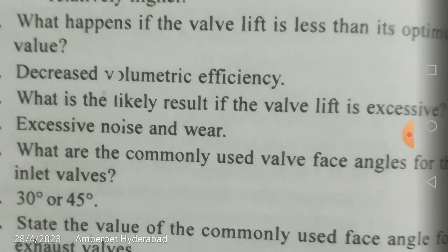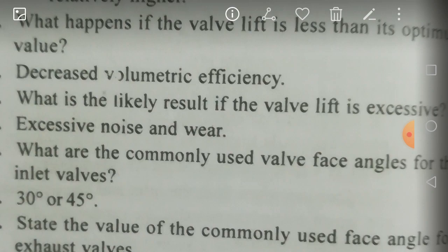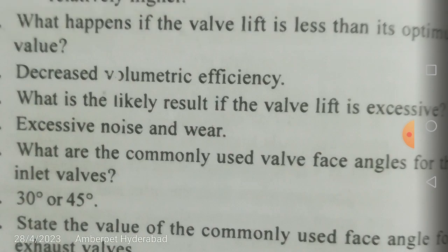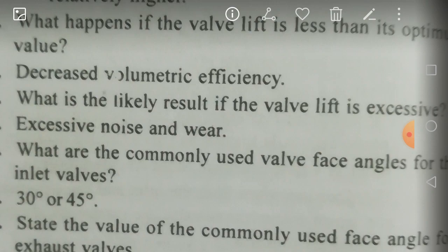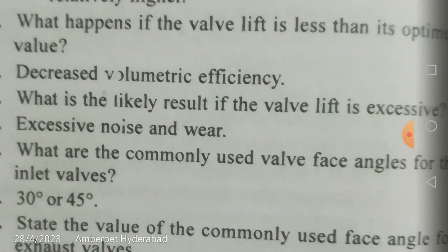Why? Because valves have inertia. So the inlet valve opening and closing is going to be more than 200 degrees roughly. I don't remember that value. Similarly, friends, your exhaust valve opening and closing is also more than 200 degrees approximately. Please check the values for the 2-stroke engine and also the 4-stroke engine. For the suction stroke and exhaust stroke, the crank angles are more than 200 degrees. For the compression stroke and power stroke, the crank angles or valve timing should be less than 180 degrees. Please check with any standard book, friends.